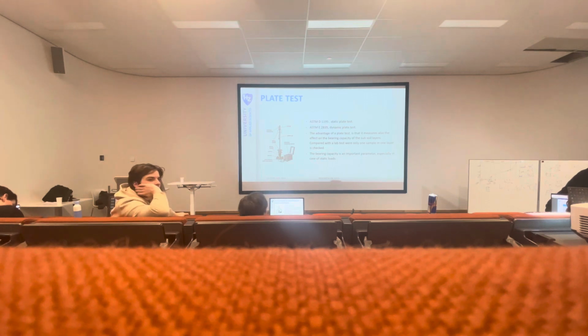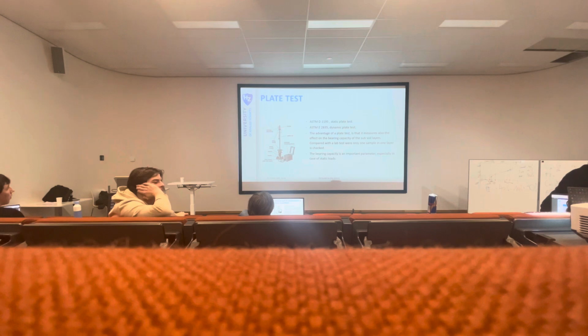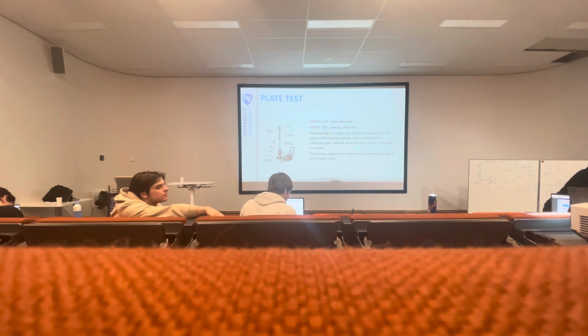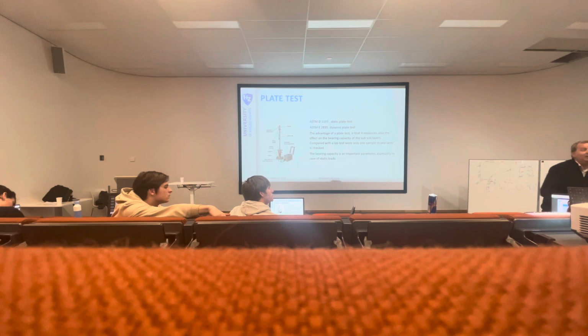I'd say you could find the dynamic better if you did this one more than the other one. Yeah, that's true. It can be very useful, but also when you do a CBR test, you grab some soil from the first 5 to 10 centimeters, and you're not testing what is beneath that. With a plate test, you get back data from what is beneath.